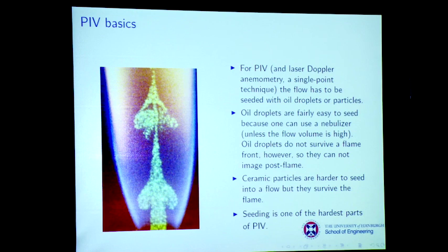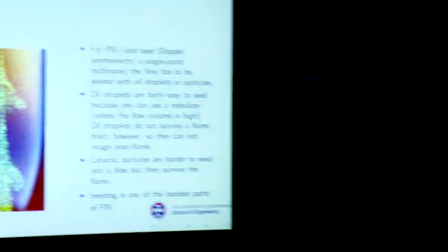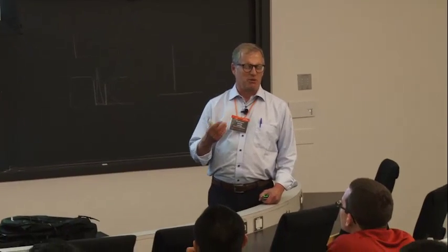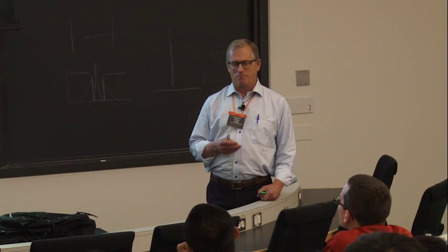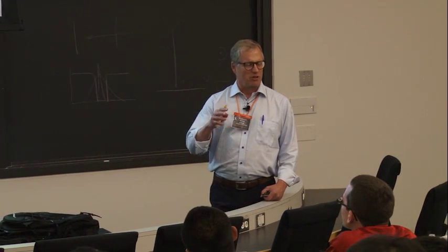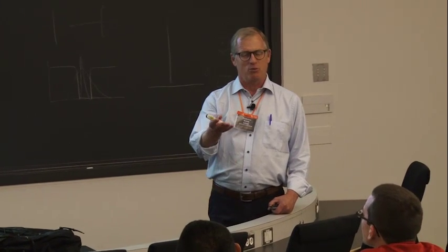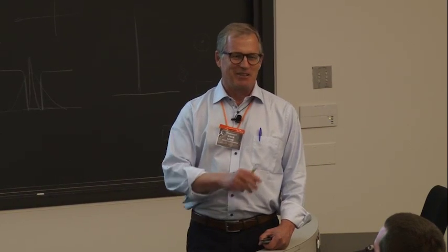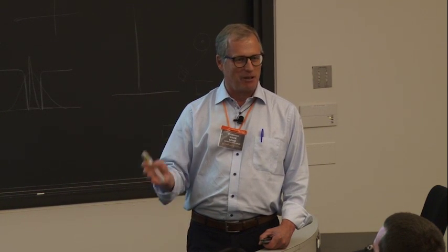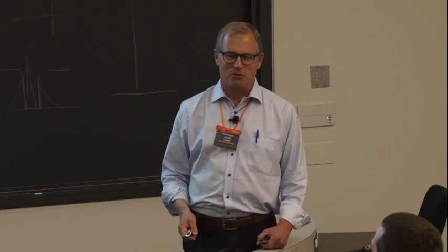The other way to do it is with ceramic particles, and those use all sorts of special little tricks to try to entrain them into the airflow. It can become very difficult. One time we did PIV in a project for people who were studying building fires. And those use basically buoyant forces, right? That's what drives a flame. Let's say a flame along the side of a wall of a house or something like that. That's a buoyant force. And if you start blowing particles at it, you're going to totally screw up the flow. And so getting particles fed slowly into a buoyant flow is very difficult.